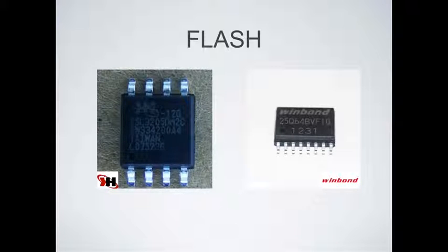So you're not going to be able to find this data sheet. The way we found it and how we looked it up is we searched Macronics for this 25L3205DM2C, and we were able to find something similar. What we came up with was that this particular chip was a 32 megabit serial SPI flash. If we hadn't found that this was the Hong Kong version of Macronics, then we would have been searching forever.